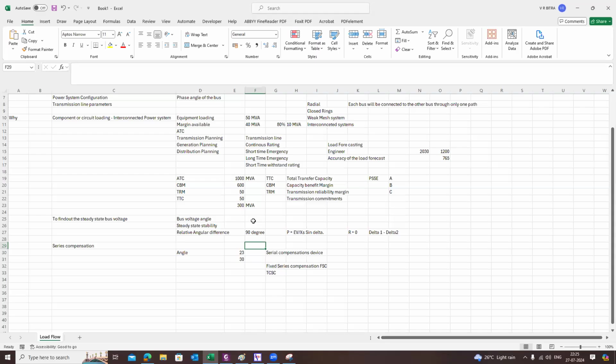But typically our systems are not such radial systems in high voltage and extra high voltage. It is heavily interconnected. So the angle cannot really change by something like 10 degree from one substation to another substation. So depending upon the length, depending upon the network, the countries came up with some numbers like 23 degree in India and 30 degree in other countries, depending upon the network size of the system. And if the network goes beyond 23 degree, then probably there is a higher probability that one bus with a higher angle with respect to another bus with a lower angle can go beyond 90 degree.